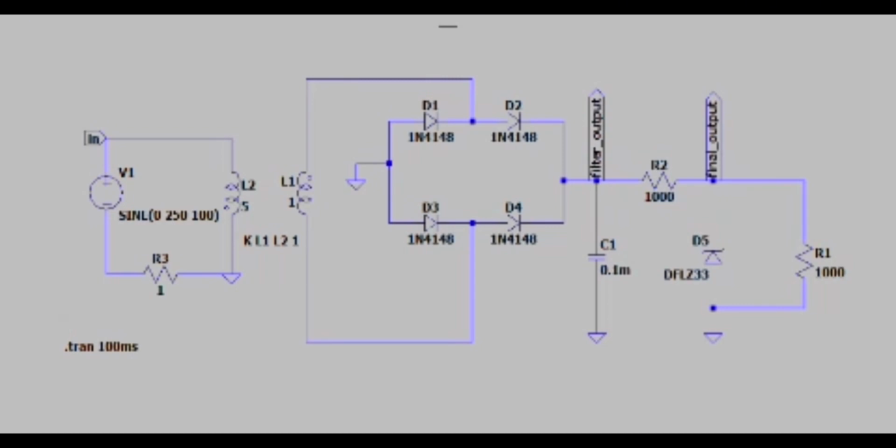During the positive half cycle, diode D2 and diode D3 are forward biased and allow the current to pass through, whereas diode D1 and diode D4 are reverse biased. During the negative half cycle, diode D1 and diode D4 are forward biased and conduct electricity, whereas diode D2 and diode D3 are reverse biased. Hence, the arrangement of the diodes ensures the current flows through the capacitor, inner diode, and output load in one direction. Since the polarity of the output voltage is the same, a positive voltage pulse will be produced in both the positive half cycle and the negative half cycle.